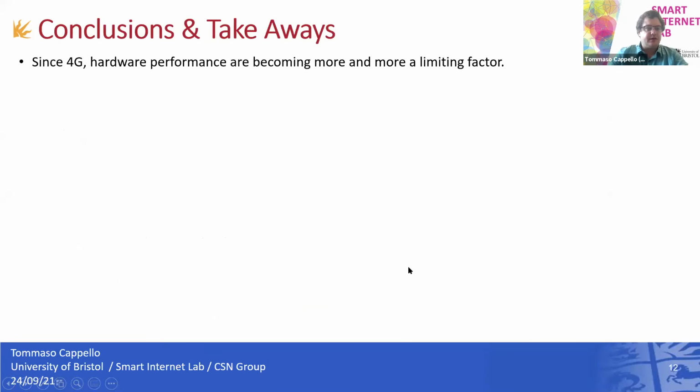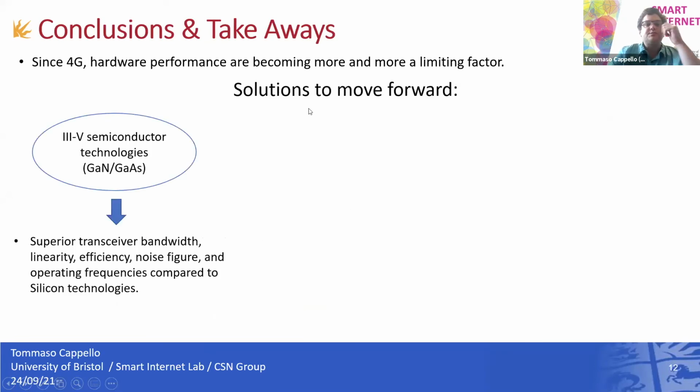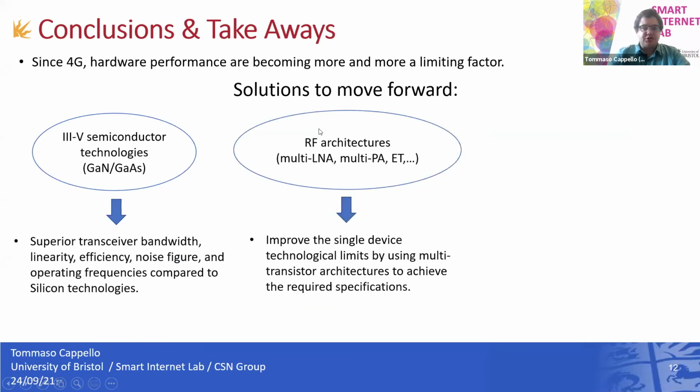so this is more or less my view regarding the future of radio frequency communication. So wide-bandgap semiconductor technologies are surely beneficial for this because they can implement very high power densities, so you can pack higher power levels in very small footprint areas. Lower capacitances mean more bandwidth, much easier matching.